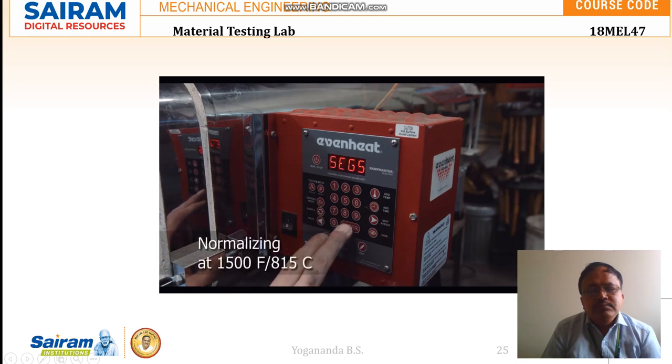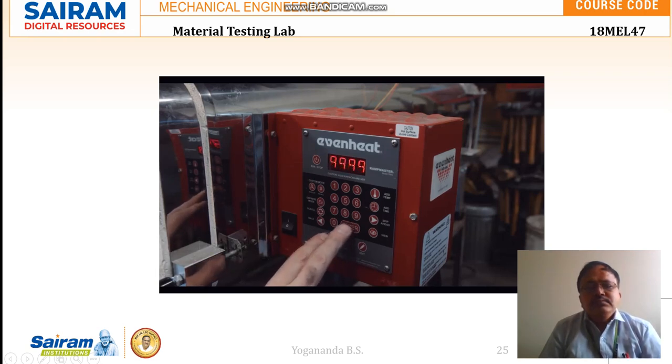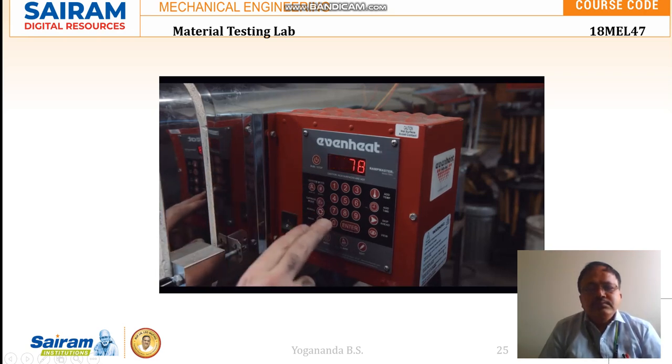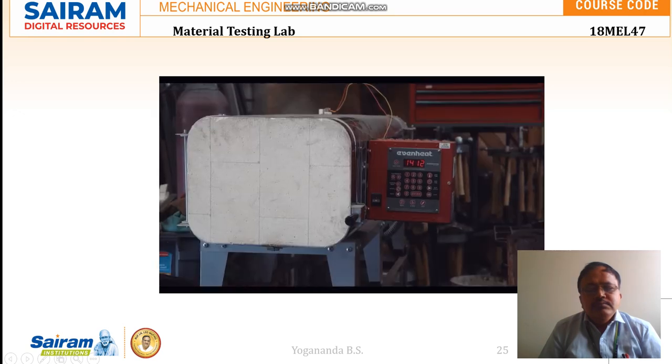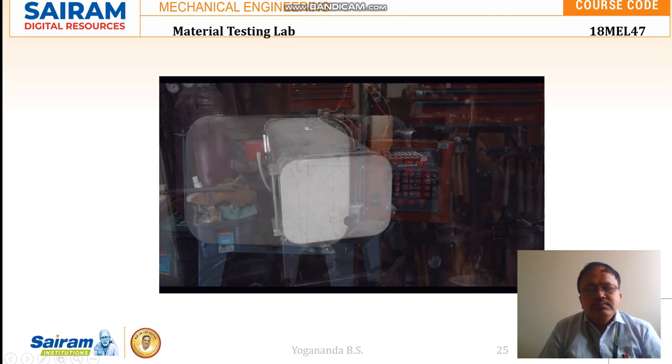Since my high carbon steel is 1075, I programmed the Ramp Master to bring the temperature to 1500 Fahrenheit, that's 815 Celsius, and hold it there for 6 minutes. To find the critical temperature of high carbon steels, you need to refer to a table that you can often find on the internet. Curiously, when searching for 1075, you will find at least 4 different temperatures, and 3 of them are completely wrong. The first step in my heat treating regime is to normalize the blade.